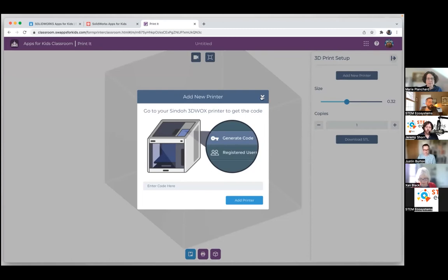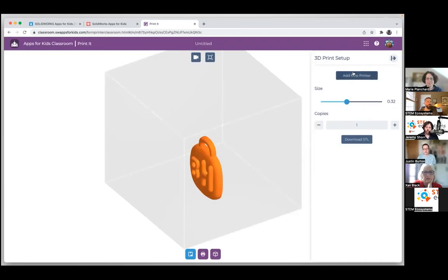And actually what they did is they took their standard settings to give the best chance of it printing straight away. So if you use this method here, there is no editing needed of the slicer or anything like that. You don't need to edit any of those things. They just choose the best settings, so supports on, attach it to the base, those sort of examples. And then they'll just print it directly. So you can get some really good results just by literally clicking print and having it sent.